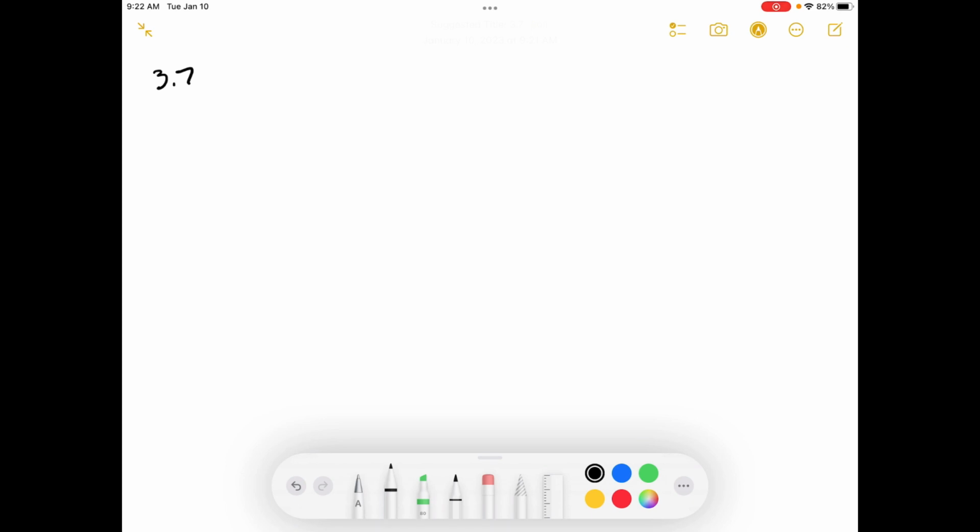In a separate experiment, an empty flask is weighed. 35.3 centimeters cubed of the lubricating oil is poured into the flask, and the flask is reweighed. If the scale reading was 124.8 grams in the first weighing, what would it be in the second weighing? Suggestion: recall Archimedes' principle and do a force balance on the block.